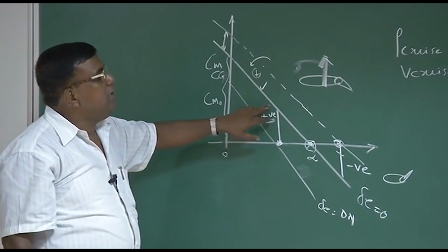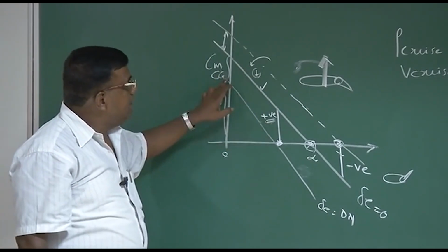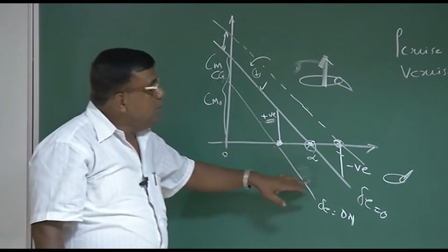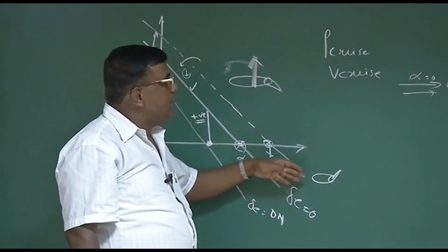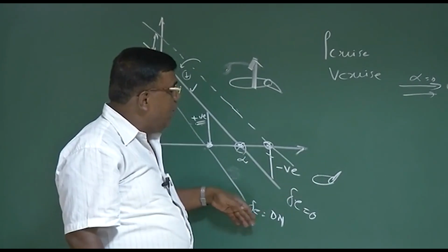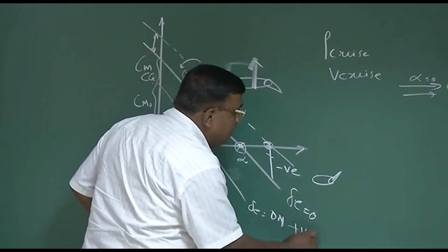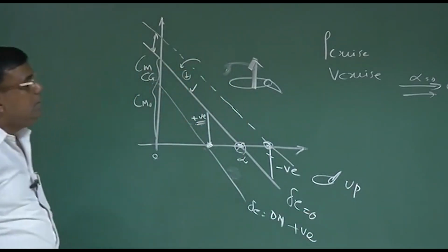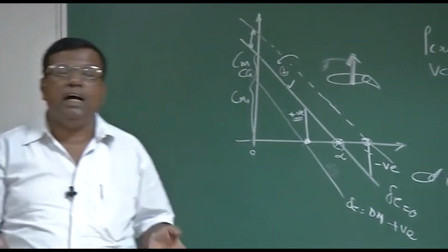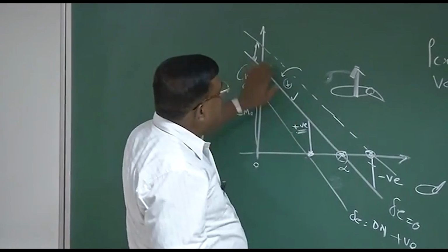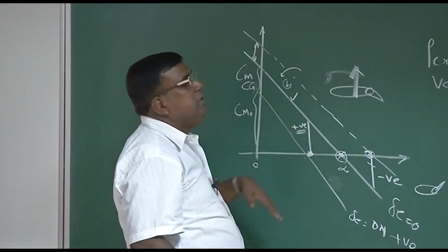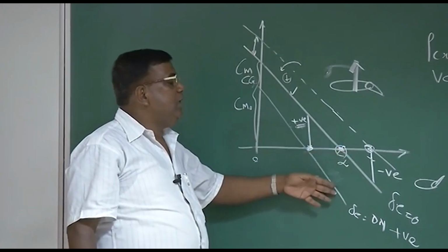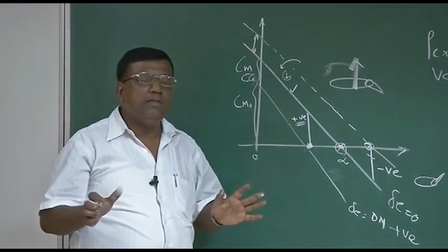So that will counter this positive moment, and I can say that this line gets shifted here, and this becomes my trim point. So delta 0 to delta negative; delta down is positive, delta negative means delta up. These are the conventions used, and if you see a chart, you will frequently find this sort of graph or variation displayed for a pilot to know, if you want to fly at this speed, what elevator is required, and he gets a feel for the airplane.